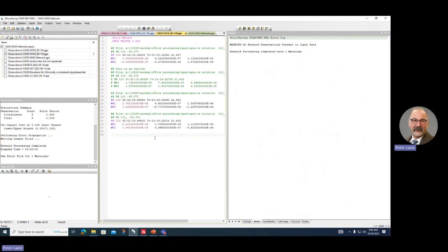Now, 3 centimeters, basically a tenth, for your vertical. I'm not going to reject the 1200s, so that's basically that. And then like 2 centimeters, 1 centimeter, 2 centimeters, like 500-600 for your northing and easting or so. But it's also going to depend upon what you're doing. If you're doing higher order control, then you're going to want to make that tighter. And you're also going to QC your vectors before you bring them into your adjustment. And we'll look at that.